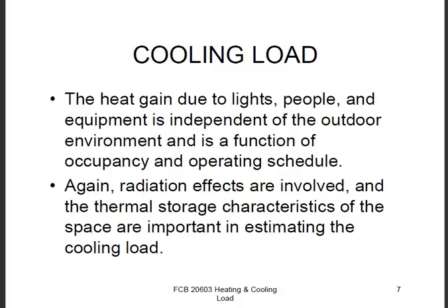The heat gain due to lights, people, and equipment is independent of the outdoor environment and is a function of occupancy and operating schedule. Again, radiation effects are involved, and the thermal storage characteristics of the surface are important in estimating the cooling load.